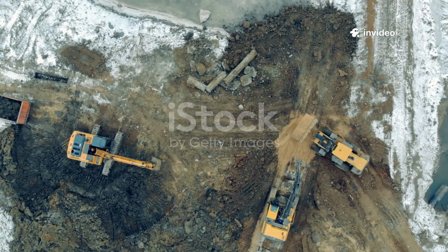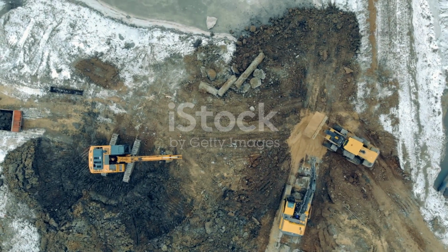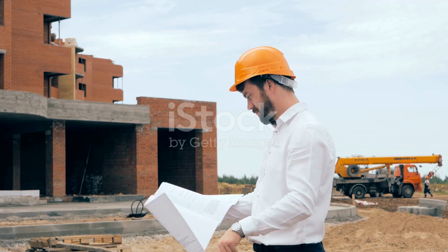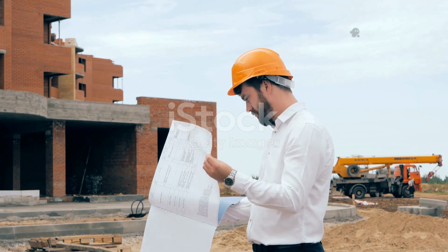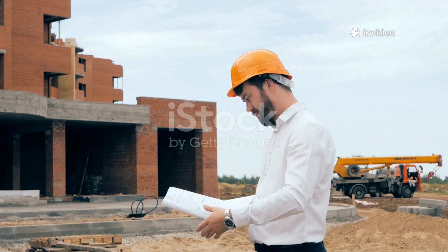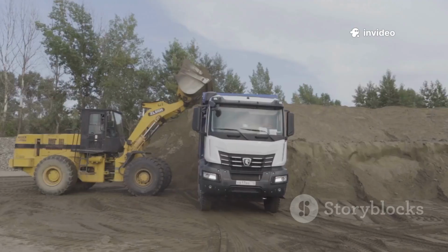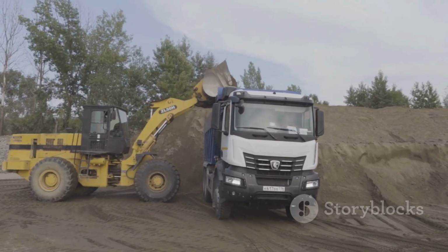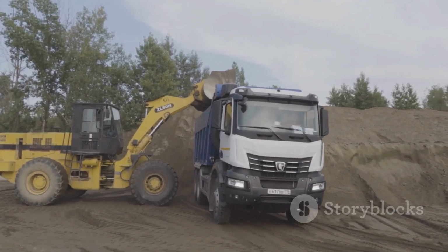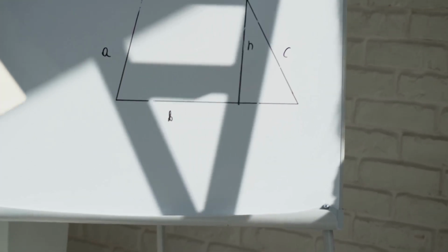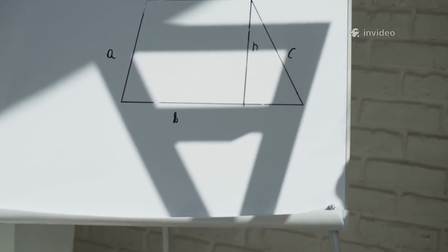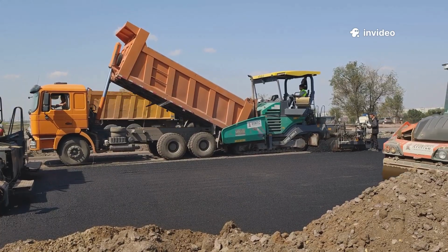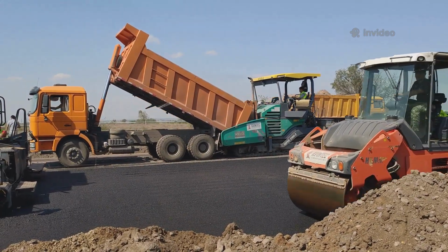Let's talk about free haul, the sweet spot of earth moving. When a contractor bids on a project, the price per cubic yard includes moving dirt a certain distance, called the free haul distance. As long as dirt is moved within this range, say 1,000 feet, there's no extra charge. On the mass haul diagram, engineers draw a line to show which dirt can be moved within this free haul limit. It's like free pizza delivery within a certain radius. The cost is built in.